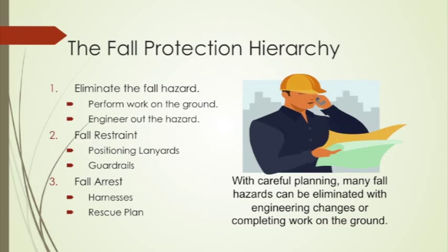Fall arrest systems are great, but there are other options that should be considered first. Can the hazard be eliminated by working on the ground? If not, should fall restraint systems such as positional lanyards or guardrails be used? With careful planning, many fall hazards can be eliminated with engineering changes or completing work on the ground.